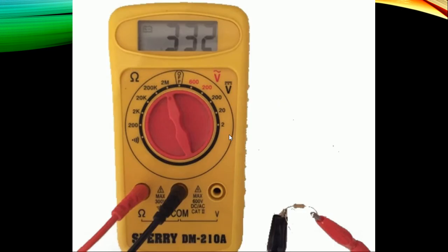Next, we have a 330 kilo ohm resistor. We want to get the value of this resistor. Of course, since in the first image you wanted to know the voltage, next we want to know what the resistance is. So we'll select the knob and then select the 2 meg, and then also the probe. In the first image, it is connected in the voltage part, but since you're measuring resistance, you have to transfer it because this is the label for resistance. And then as you can read, because this is a 330 kilo ohm, it's 332.